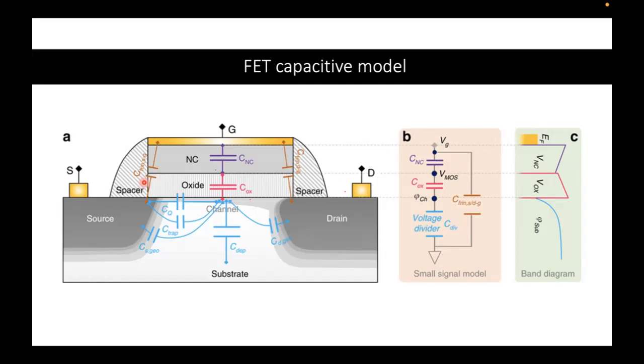So we are exploring the capacitance model at a subtransistor level. For example, we have an oxide layer here, which will create by default a capacitance. We have a depletion capacitance due to the channel. We have an overlapping capacitance due to the overlap between the gate oxide and the source and the drain, and so on.